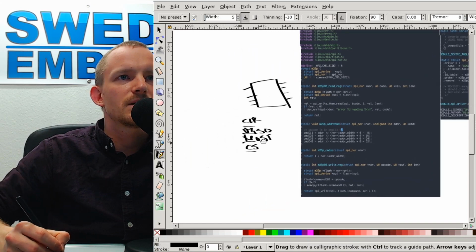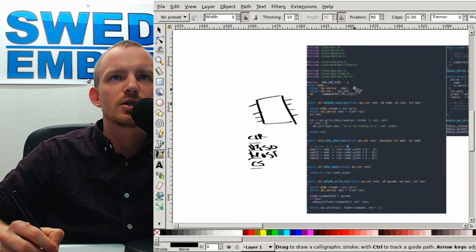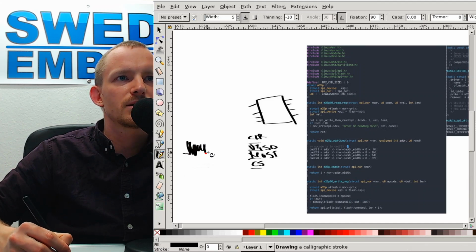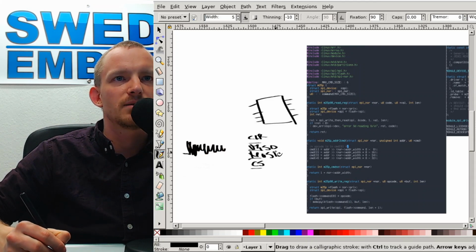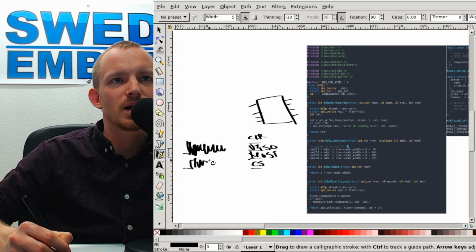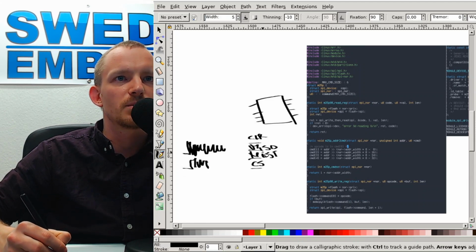So using these 4 signals, the chip can communicate with the Linux computer, and the Linux computer will basically send a bunch of clock cycles, and then it will send master out, slave in on this. This is the outgoing signal to the chip. It will send a command. Maybe it will tell the chip to read data at a specific address, and then the chip will reply on the master in, slave out, while the master is clocking the signal here. So this is SPI.